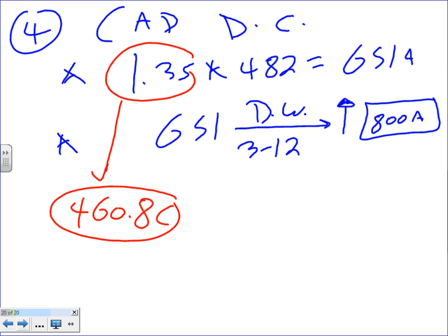At 1800 RPM, the kVAR that I need is 75. Can you guys see that? That's it. You don't need to do any calculation. From this table, all you have to do is find the horsepower here, and the RPM here, and I found 75.